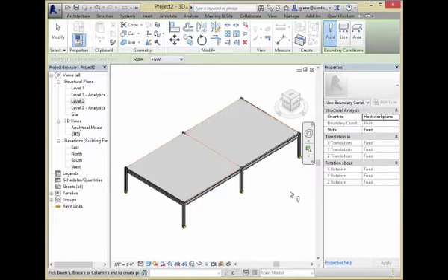The other thing I typically do with this is I go through and I put some loads on. And it's going to sound weird, but even loads are a BIM modeling object. In structural engineering, we tend to think about there being dead loads and live loads. For example, us dancing around on top of this floor, we're point loads, but we use an overall average for what our load is in terms of distributing across the floor. It'll be around 40 pounds a square foot for a residence. It's different for different types of uses. In a heavy-duty storage place, it might be 60 or 80 pounds a square foot. In a library, it's higher, but 40 pounds a square foot is, at least for residential, what we typically assume as a load. So, general purpose people walking around and working.